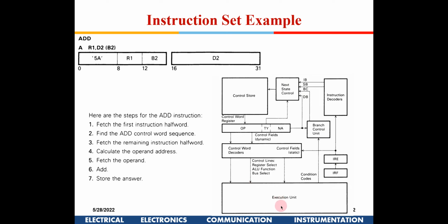While the execution unit is doing a set of tasks, parallelly the control unit prepares itself to give the next set of control signals to the execution unit. So in a way, the control unit moves one cycle ahead, trying to keep the instruction sets ready, so that the overall speed of the microprocessor is fast. So that is what we saw last time.